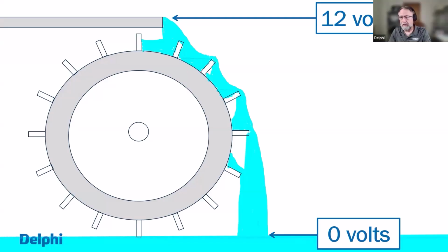And then finally, when it reaches the battery's negative post, that's when it's basically at 0 volts, and we'll call that ground. Well, no, pardon me. The battery negative post needs to be considered to be 0 volts, not the chassis. And there's a reason for that, and it has to do with voltage drop. More on that in just a little bit.